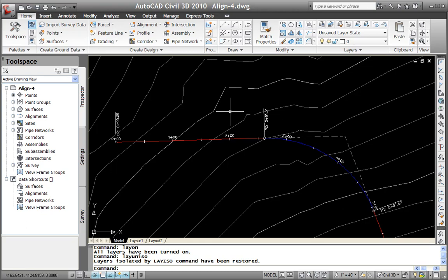So what I want to point out first is, remember, if you've been working with AutoCAD-based products for a while, we have what's called noun-verb selection. So what that means is I can either pick an object and then perform an action on it, or I can select the action or command I want to perform and then select objects to apply that command to. So the ribbon works differently for these two different modes.